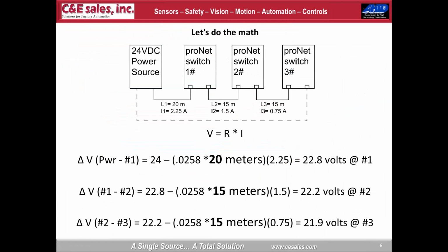This is just something to consider should you be putting these on a long conveyor line or a very large module. But also I'm using the PF10 connection with the smaller power connectors. The PF11 connectors might allow you to use larger conductors, so you could probably expand these even farther than what you see in this little example I came up with.